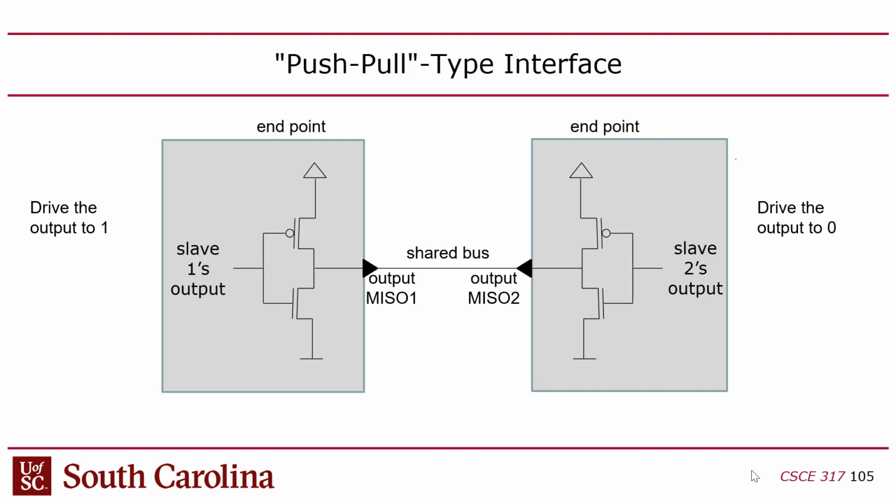Okay, so you obviously build gates out of these things, but you also build drivers to set an external pin to 1 or 0. I'm talking about SPI, where the clock, MOSI, MISO, and slave select are connected to a driver. One way to build them, the obvious way, is using what's called push-pull logic. Say I have 2 chips, and they're both driving MISO. How do they pull that wire to 1 or 0? Well, they connect it to an inverter, basically.